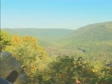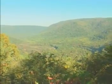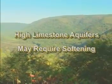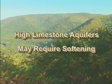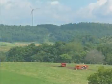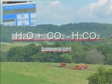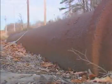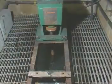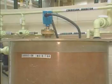Depending on the geological formation surrounding the groundwater source, the water may need further treatment. For example, in areas that have a high limestone content, the water may need to be softened using an ion exchange unit. In other areas, the water may be exposed to carbon dioxide, which interacts with the water to give it a lower pH, making it more corrosive to the metal pipes in the distribution system.